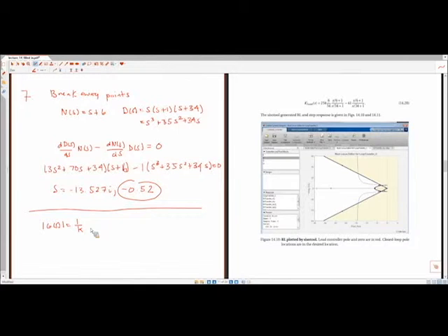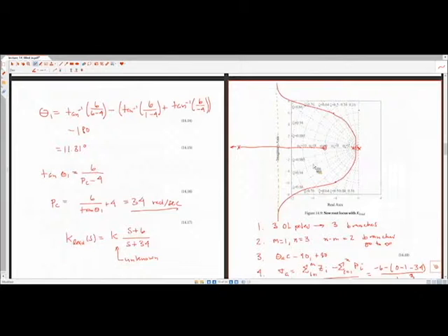So this allows us to compute k as the inverse of the magnitude of g of s. Going way back to lecture 2 and homework 1, we know how to calculate the magnitude of a function of complex numbers by looking at a bunch of vectors going to this point in the complex plane. Here is s. S is equal to negative 4 plus 6i.